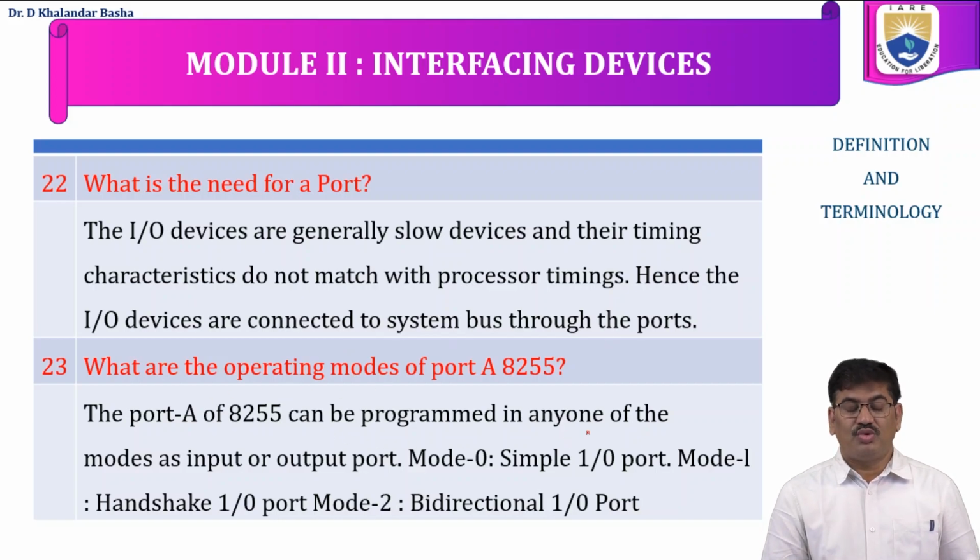What are the operating modes of 8255, that is the programmable peripheral interface, for port A? Port A of 8255 can be programmed in any one of the modes as input or output port. That is mode 0, which is simple I/O mode, mode 1, handshake I/O mode, and mode 2, bidirectional I/O port with handshake signals.